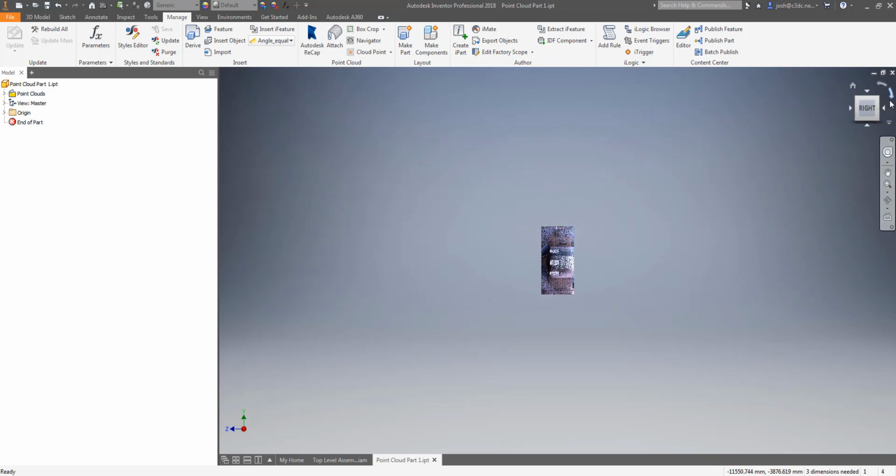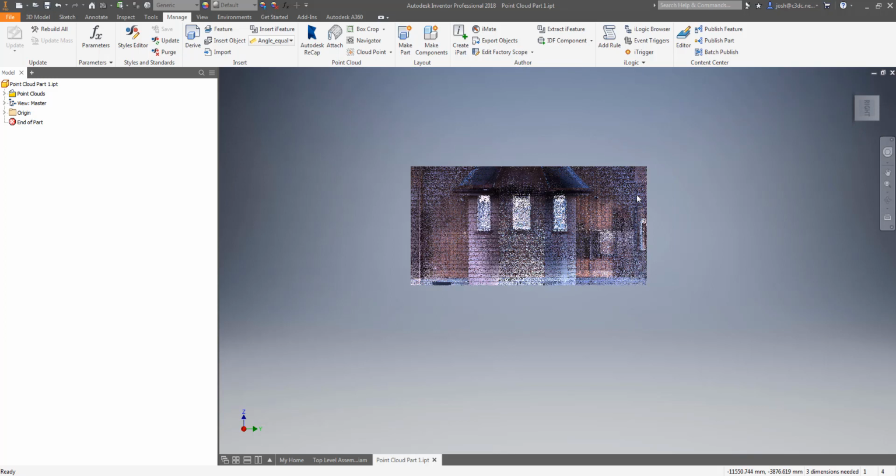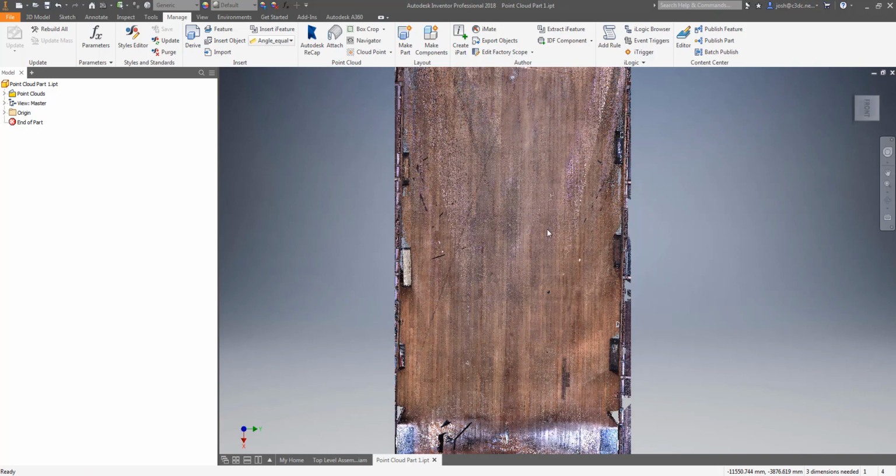This is also why it's best to take a slice through the point cloud at a level you'll be working at. If you take your slice through at the bottom of the wall, and the top of the wall is 10 to 15 millimeters off vertical, that means that you will either need to adjust your model again later, or your new model will be 10 to 15 millimeters wrong.